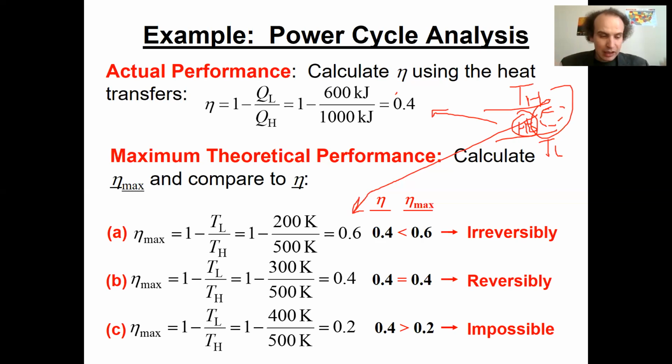So when you read some proposal which says my efficiency will be 50%, right? Let's say you read and it says 50%. And what should you do to check it? You may go through all details, but find Carnot efficiency for this setup. And if your Carnot efficiency will be 55%, then, well, you may open it and start reading because you can say nothing at this point.